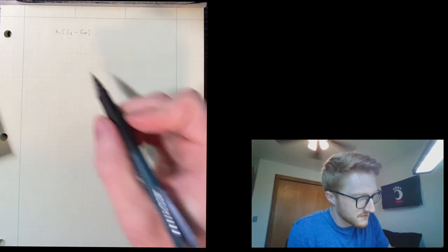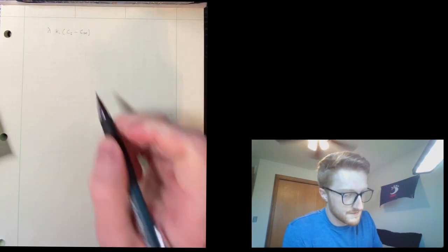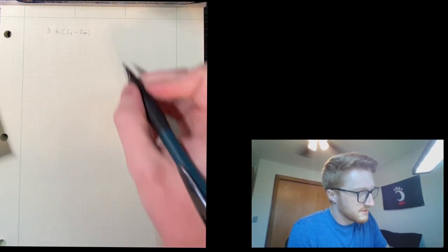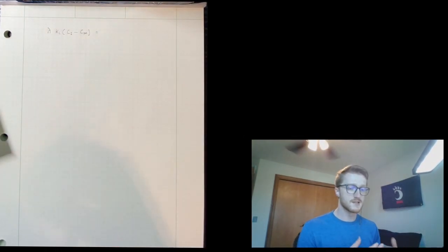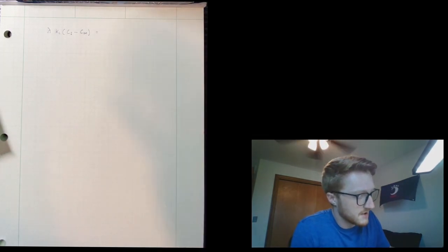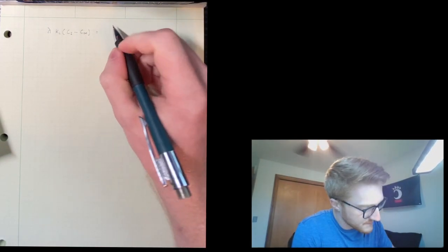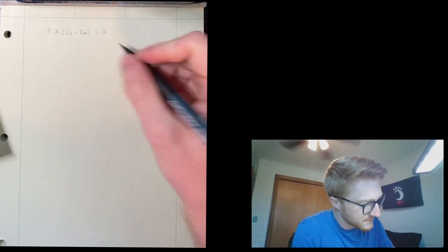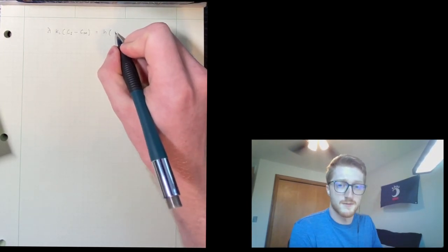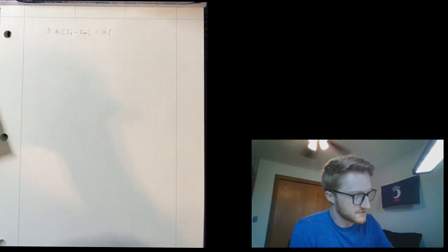So you have a heat of vaporization, and this is your water evaporating in a mass transfer setting, and then you need the heat supplied from the air to the surface as a heat flux in order to cause this evaporation. So we can write that as a heat transfer coefficient times the difference in temperature from the air, which is going to be higher, to the temperature at the surface.